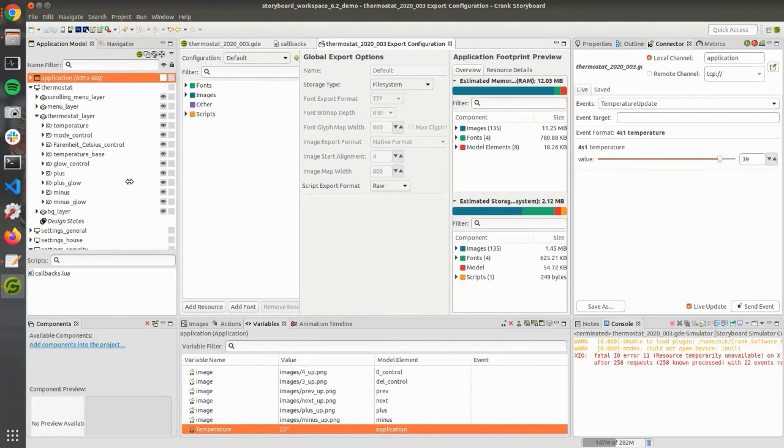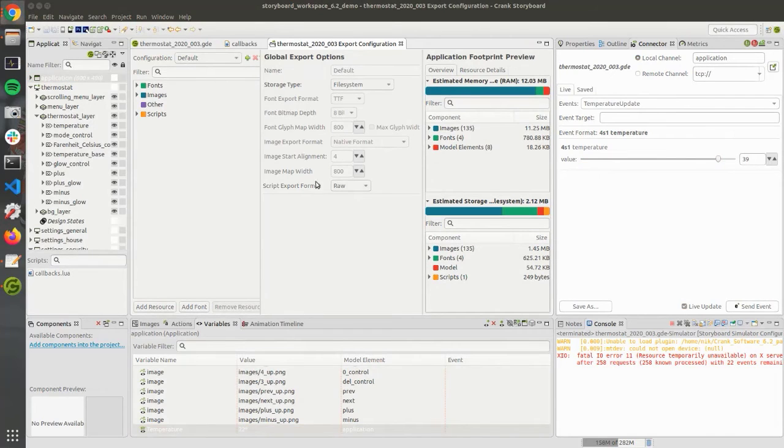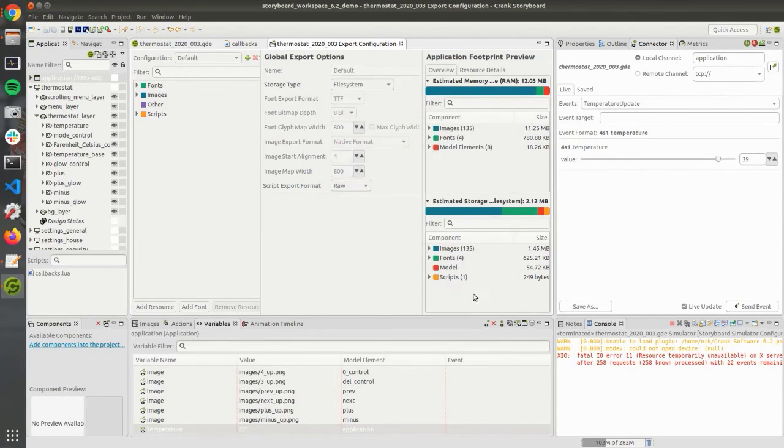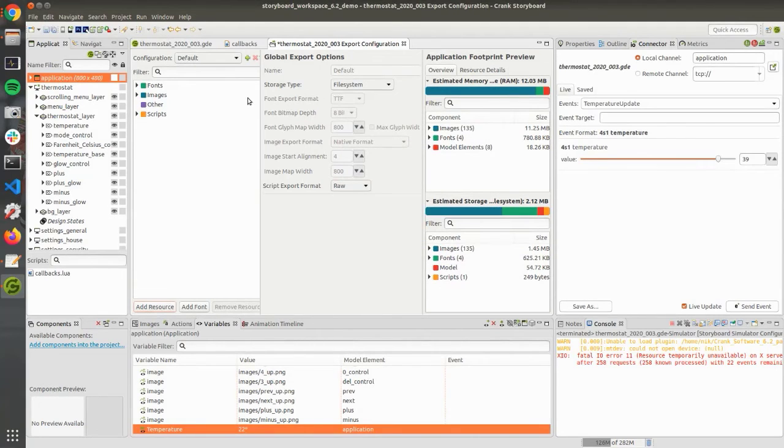So in this case, you can see here, I've got an export configuration. It's targeting what I would say is a higher level embedded system. So something like embedded Linux, WinCE, QNX, something like that. So probably an MPU, there's memory protection, features, things like that. But we can start defining the resources that we're including. So if you wanted to, include all of your scripts and your images, things like that, you can set those there, fonts, say, okay. You can start choosing other properties.